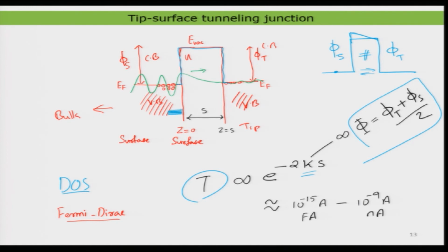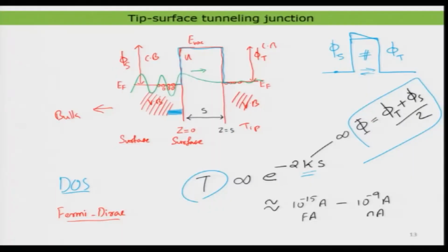Well, you know that the valence band and conduction band, although you call it a band, if you zoom inside, you would find that they are actually just discrete levels. But of course, you do not distinguish them, because their energies are so close that you cannot really distinguish them. Therefore, there is a term that is normally used in solid state for defining the number of available electronic levels that are present in the band, which is known as the density of state.